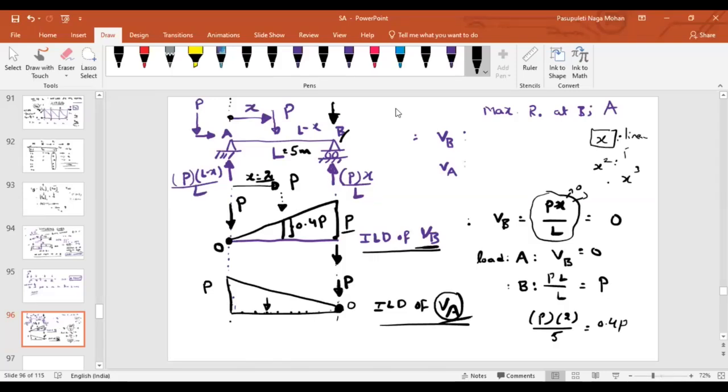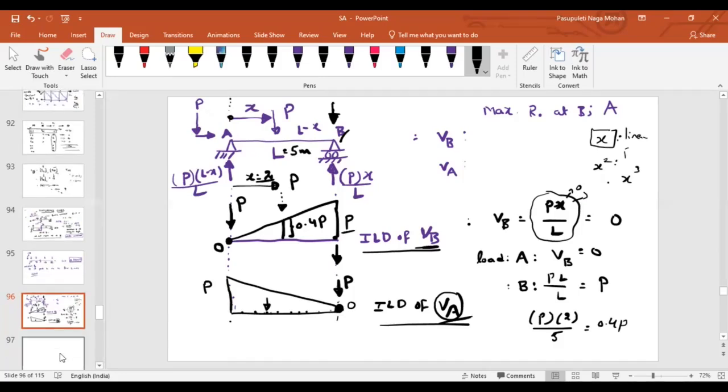If the load is acting at point A, what is the reaction at A? Minus P, sir. Minus P. Any other answers? Plus P, sir. How come it's minus P? Sorry, sir, plus P. Upward, so upward will be plus P. Also right. Plus P, yes. It's clear, right?